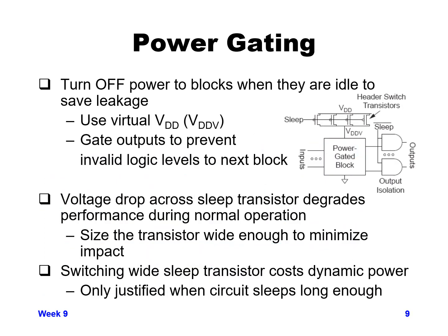And finally, the best way to reduce your leakage is to use what's called power gating. I kind of mentioned this a slide or two ago. In effect, you can use a parallel set of transistors that are in series with your voltage supply, your VDD supply, and you make a lot of these parallel transistors.